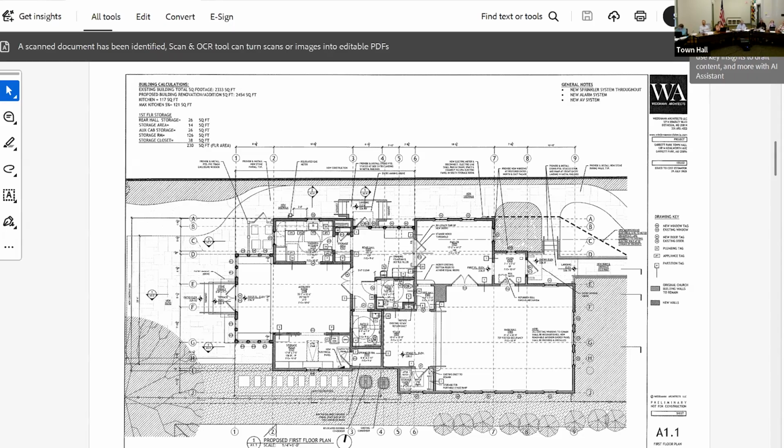One unfortunate thing is that because it's a commercial building and it's being sprinklered, it requires a 4-inch water line from the street to the building. Oh, wow. What do we have now? About a 1-inch. If this were a house, you could do a sprinkler system with a 1.5-inch line. It's the fact that it's a commercial building. 4 inches is the minimum.